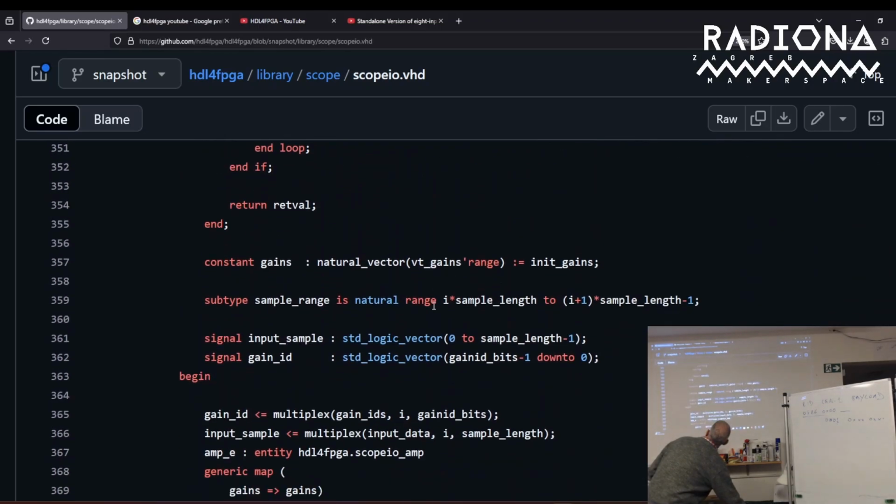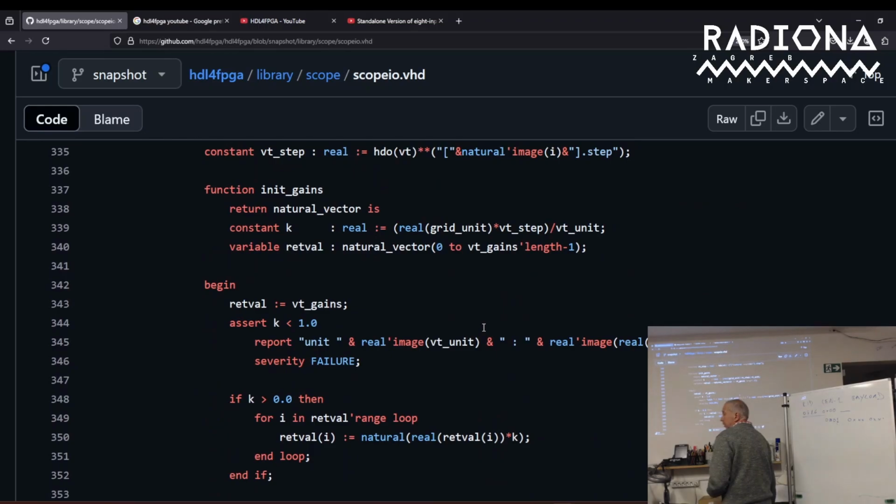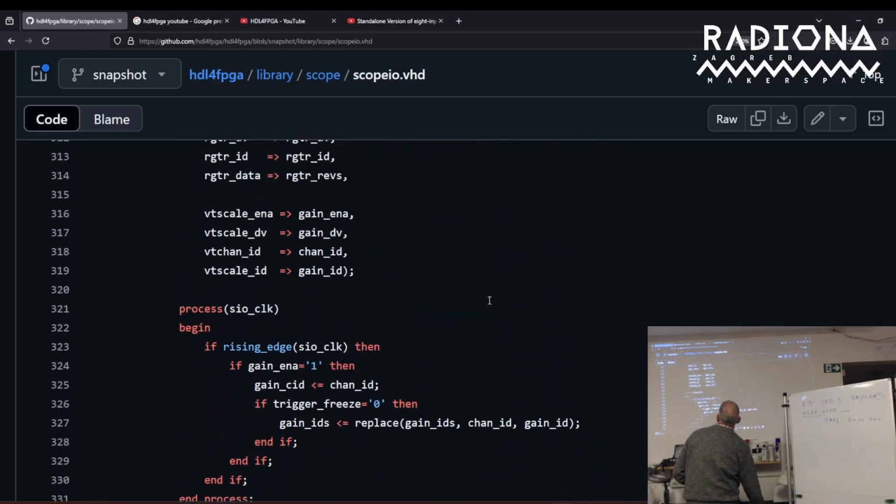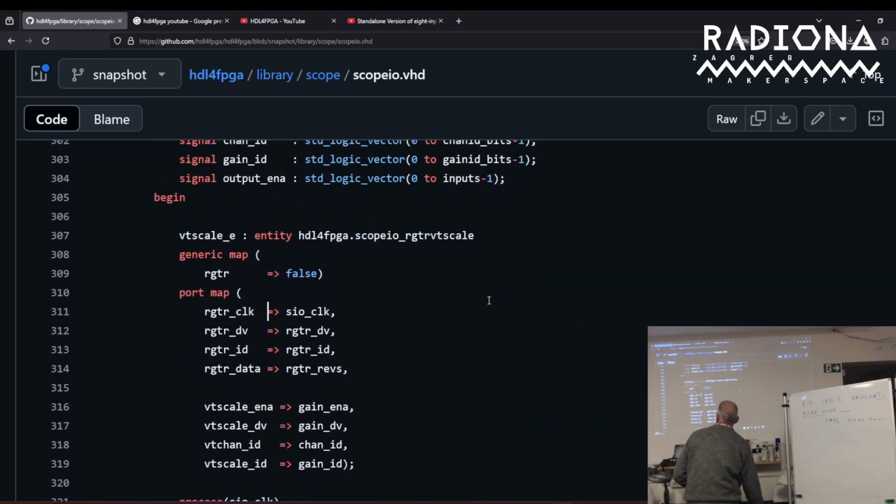So the trigger unit module has internal registers, and we are somehow addressing and filling, or reading and writing, these registers. Yes, the register is in real time, not in synthesis time. That's how we can set the trigger to change the level, to change the inversion, and so on.